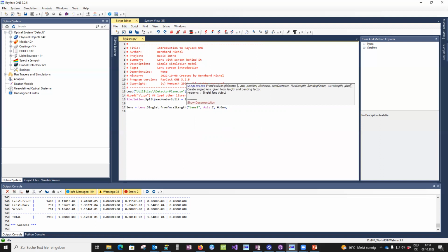So we can use units and should do so, but the default units are millimeters anyway, so I could have left that away here. For the thickness, I use another technique, so-called keyword arguments, in order to make the script easily readable. Let me choose here 4 millimeters for the central thickness.